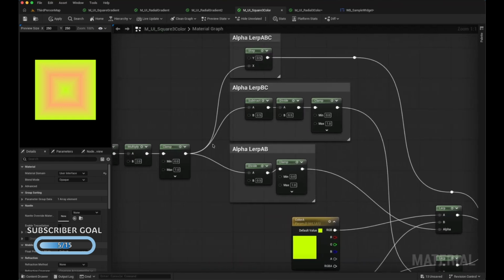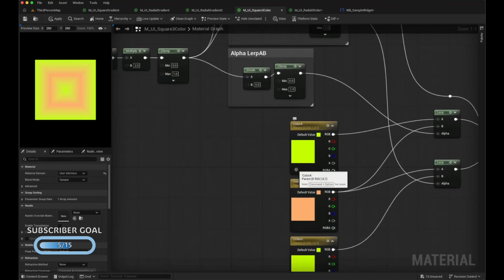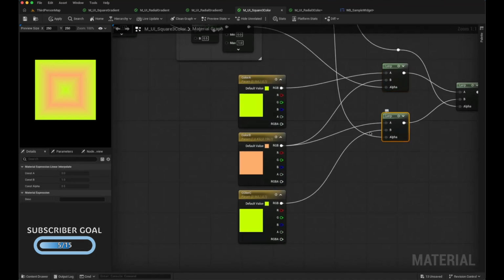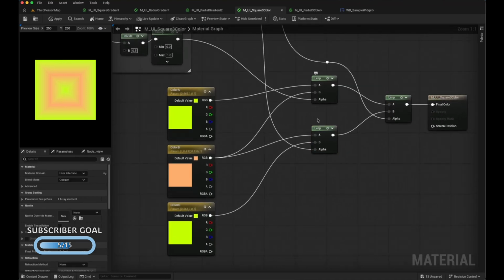For 3 colors it is a bit tricky. Everything remains the same until the first clamp node. This was our alpha value for 2 colors. But now that we have 3 lerp nodes, lerp AB is for color A and color B. This is our lerp AB. Lerp BC will be for color B and color C. And then we have one more lerp that will combine these both lerps.